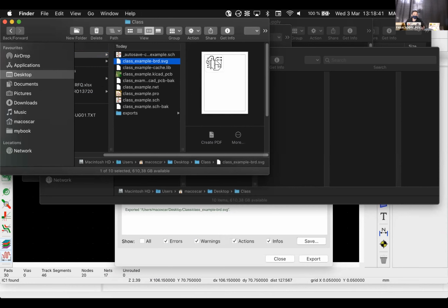So here we have 2 options. The option that we push for is Inkscape, because it's open source, and in this case it works better. Or if not, Illustrator or any other vector software, okay? The problem with Illustrator is that when you import it, it doesn't import well the size of the tracks and everything, so it's messy. So I encourage you to use Inkscape instead, okay?